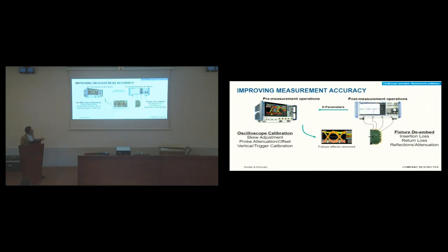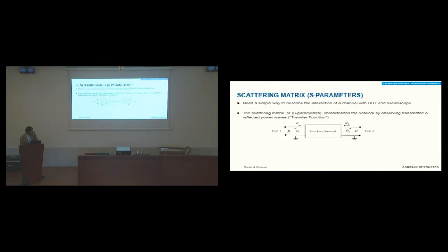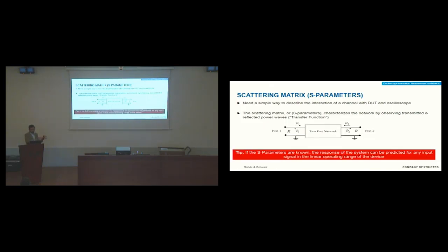So we calculate the S parameters, we load them into the oscilloscope, and then we de-embed. As I told you, S parameters are very common in high frequency device characterization. Once we have the S parameters, as long as the signal is working in the linear range of the devices involved, this parameter matrix can be used.